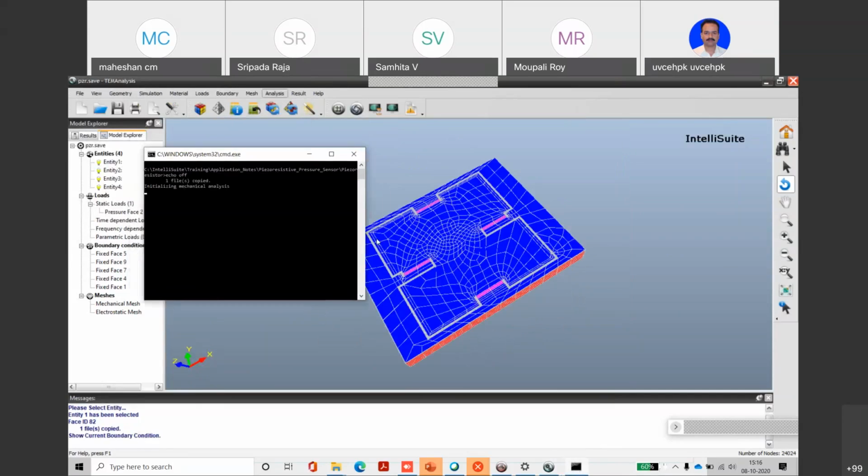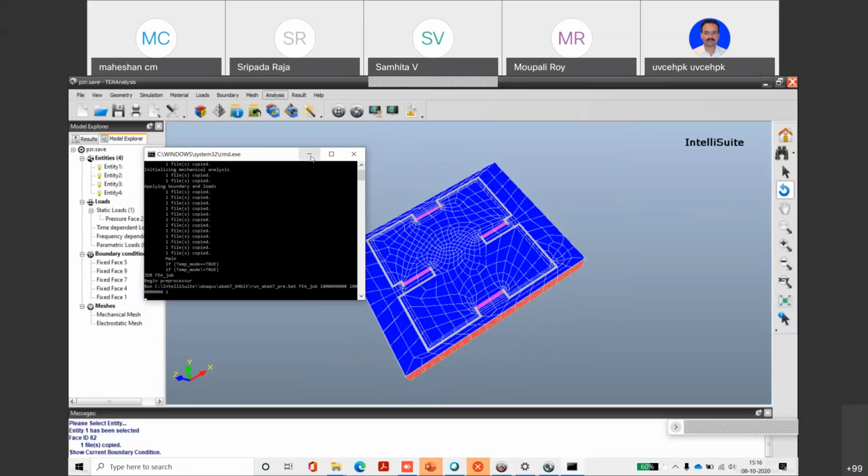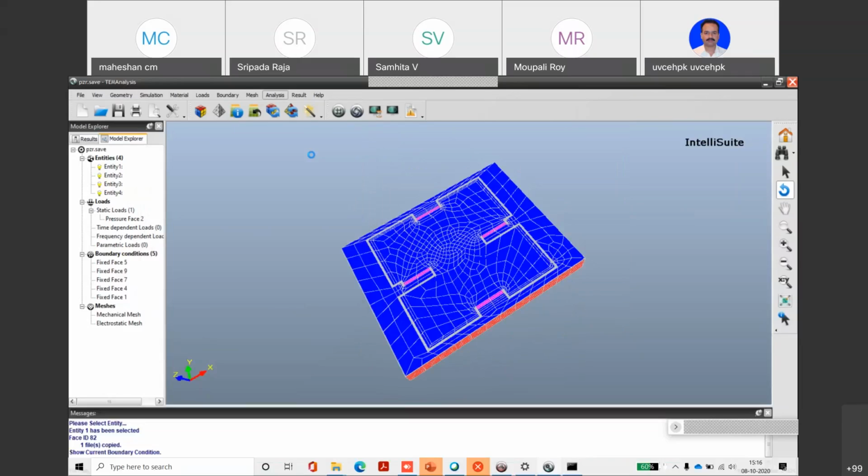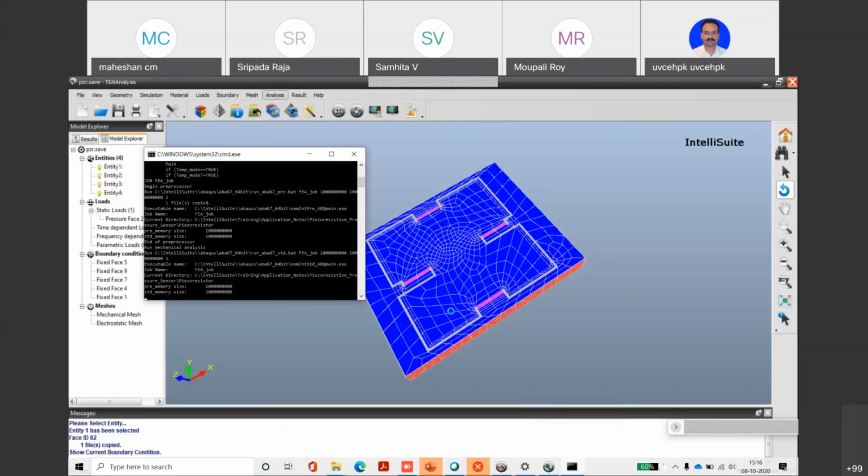Okay. I was also telling you that we have applied piezoresistive coefficients to the wire also, but we have maintained it as 0. The reason we have done that is because when we do the electrical simulation, we take only the electrical part of the device. Which is the electrical part of the device? It is resistors and wire. Okay, we don't take the whole device again.